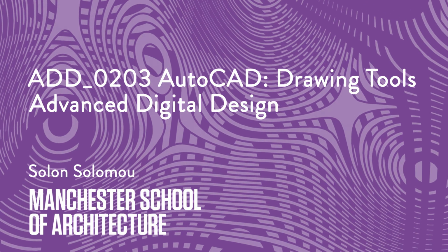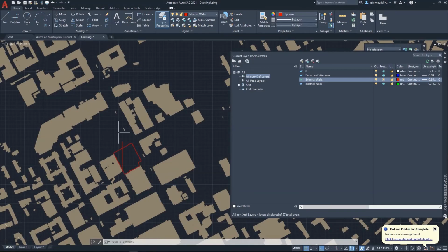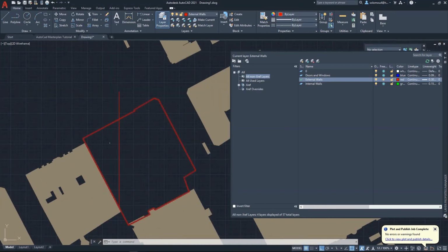So it'll be a lot easier for us if we switch around so that we can draw where this is flat rather than drawn sideways. So what we need to do is, if we type the command UCS, right? So here's our coordinates, and then we've drawn this line vertically up here, and this is our side line. So what we do is we'll click there and we'll say that the x coordinate is going to be perpendicular to that, which is here, whereas the y coordinate is going to be across there, the side.